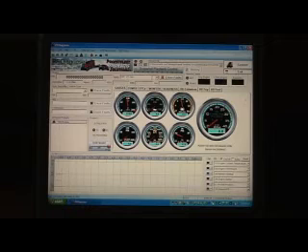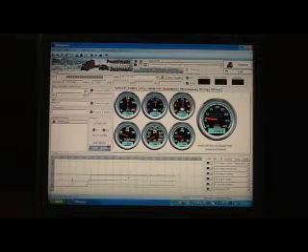Shortly after you select the connect button, you'll start to see data filling the boxes: the engine make, the VIN number, odometer, and if it's heavy duty, hours. You may even see the gauges start to respond. You'll also see the graph moving, and this is an indication that you have successfully connected. In the protocol box here, it will show the protocol that you're currently using, and the transmit and receive light should be flashing at that point.